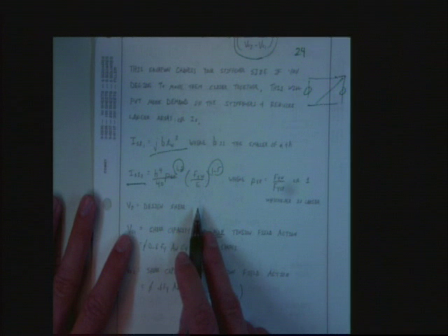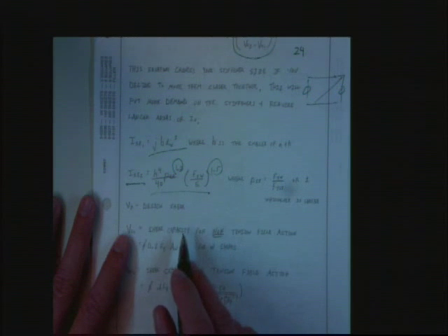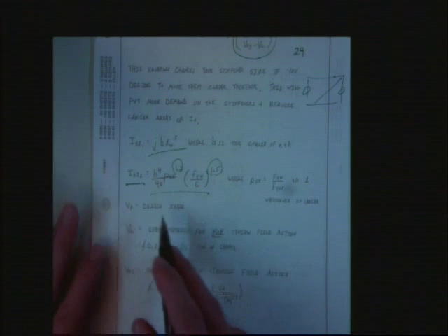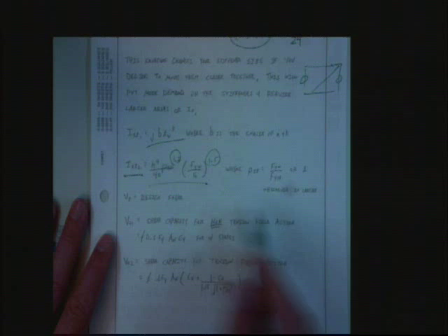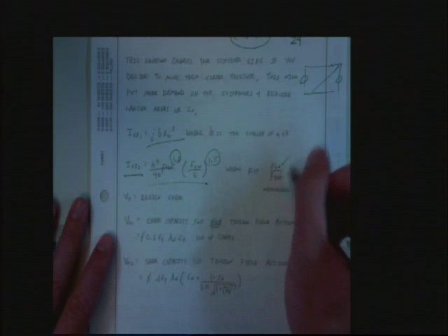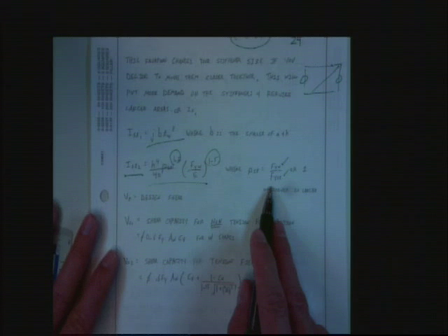Or, my favorite, we ran thousands of finite element models and we fit curves to it. That's also done often. I think that's how they got this equation. So that's what the numbers are from. And it's I_st2, h, that's just the depth of the web. ρ_s2 is only if you have girders with different yields in the web and in the stiffener. Not sure why you do that, but you might.